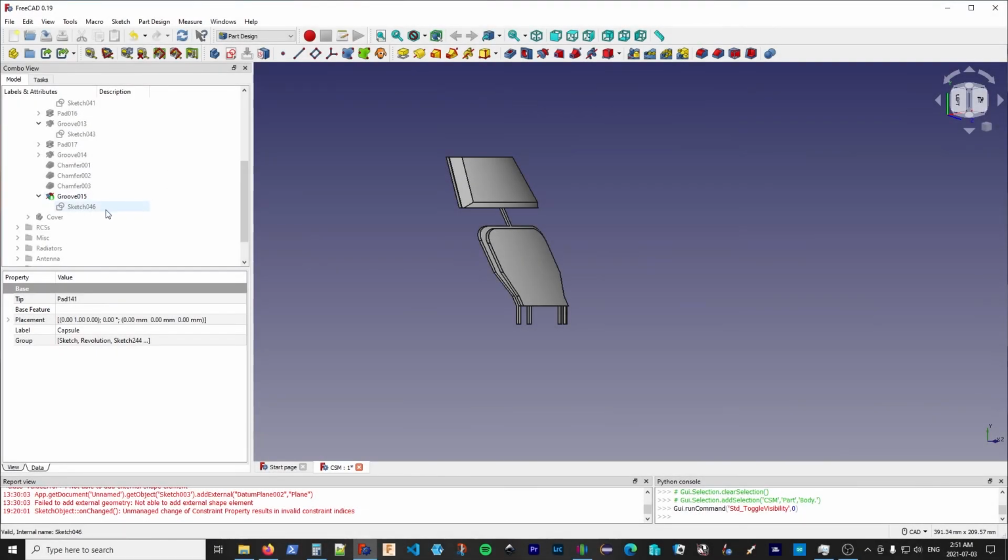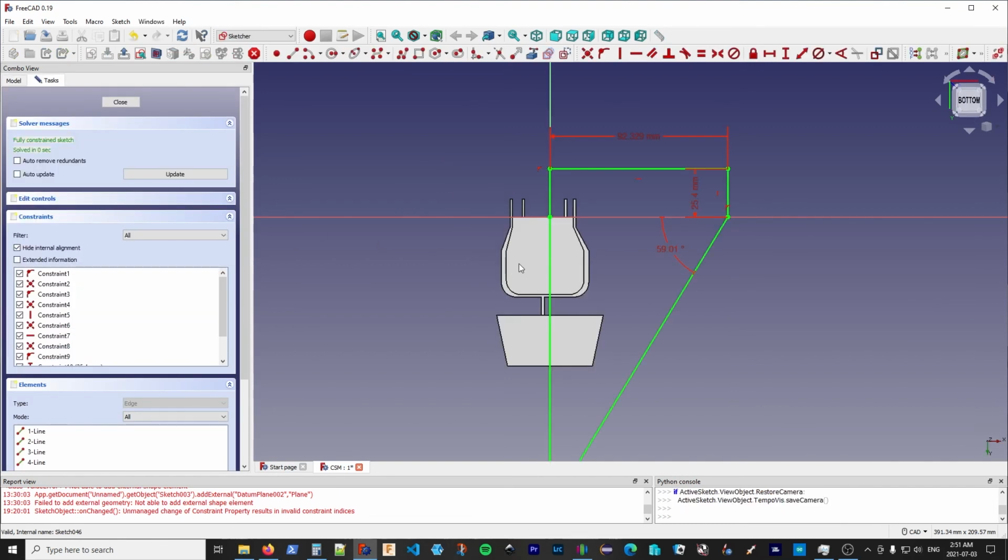Another interesting thing to consider is actually the shape of the grooves. Okay, so in this case, we just have a straight line for our groove because it's a conical cone. If you are using something like an ogive or parabola, then this would have to be a matching ogive or parabola offset from the edge by an appropriate amount. Okay, so we'll talk about generation of these in an upcoming video as I write a feature for the Rocket Workbench that can generate it. So hopefully you'll see that soon.